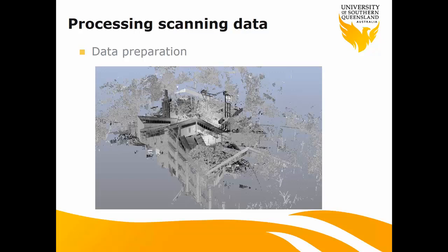After you finish the field work, upload your scanning data to the software. Usually the manufacturer will provide some kind of pre-processing software. It's mainly for scanning point registration and georeference, with very limited functions for 3D modeling. It is mainly for registration, georeference, or other pre-processing, and cannot do complicated modeling tasks.